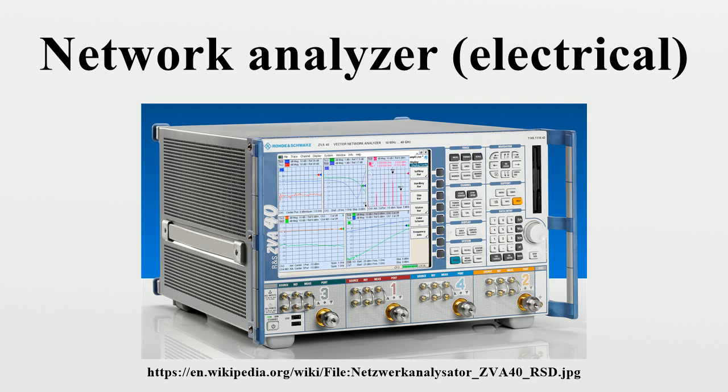The test port connectors provided on the VNA itself are precision types which will normally have to be extended and connected to P1 and P2 using precision cables 1 and 2, PC1 and PC2 respectively, and suitable connector adapters A1 and A2 respectively. The test frequency is generated by a variable frequency CW source and its power level is set using a variable attenuator. The position of switch SW1 sets the direction that the test signal passes through the DUT.